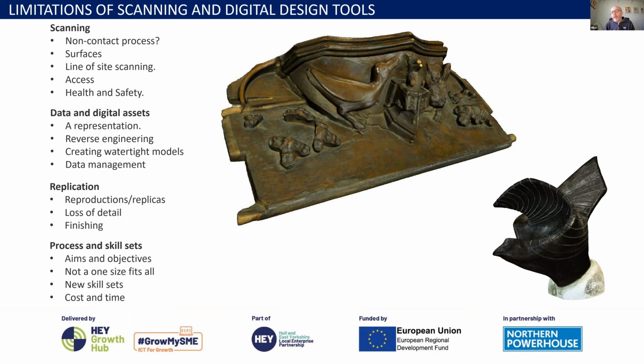Most importantly, though, is data management. How you plan to manage really large data sets and exchange that with the customer. If we're scanning something, we want to preserve all that original data as best we can, but we also need to provide our client with access to see this data. So we use various platforms to do that, such as ViewShape and Sketchfab, to help our clients have immediate access to look at their data. Or we use the Matterport system to create these dolls houses of virtual immersive environments.